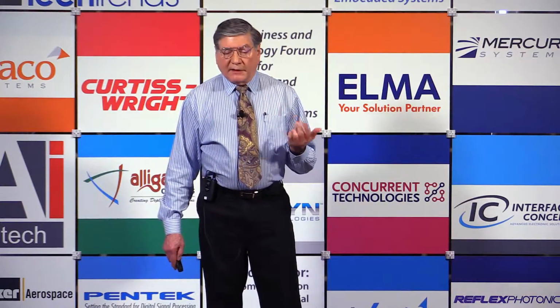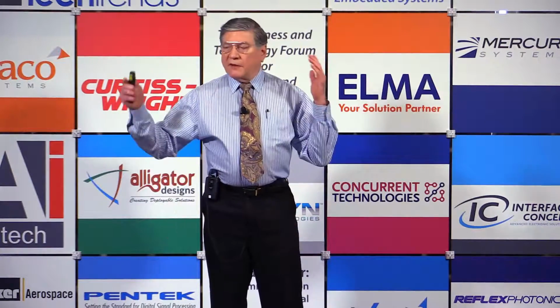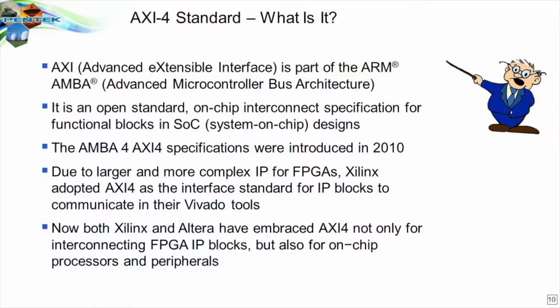And so the whole thing is that it requires a lot of design on the board developer's part to make it so that these difficulties and complexities are completely abstracted away from the user. So it really takes a lot of work. When we deliver this product to a customer, he doesn't even know how to spell JESD. He doesn't care. He just wants to get an A to D converter into his FPGA and then out. So it's a challenge, but it's the challenge that's moving forward that everybody has to face. Now, another standard that's helping us as FPGA developers is the AXI4 standard.